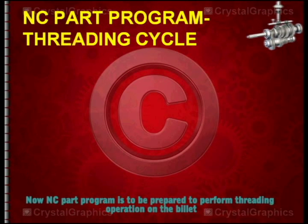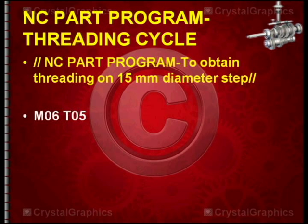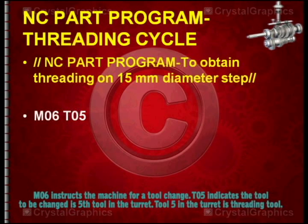Now an NC part program is to be prepared to perform threading operations on the billet. This program is prepared to obtain a thread on the 15 mm diameter step. M06 T05. In this block, M06 instructs the machine for a tool change and T05 indicates that the tool to be changed is the fifth tool in the turret. Tool 5 in the turret is a threading tool.